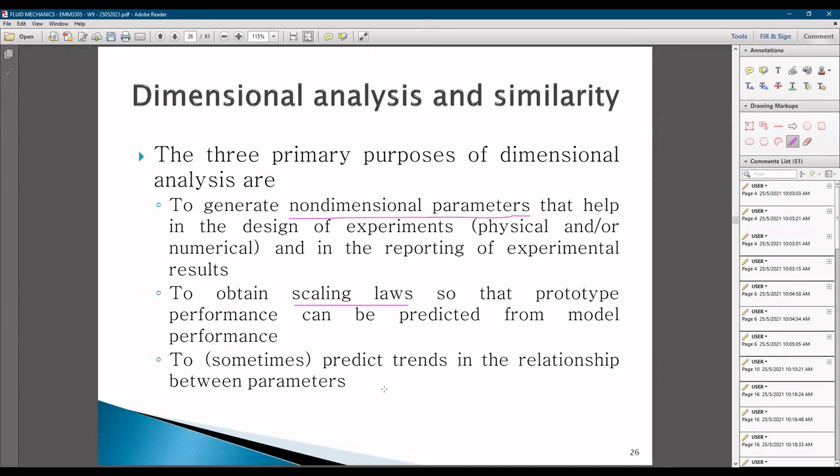Let's say at point A the velocity is very high, and at point B the velocity is low, and you can easily notice that at point A the velocity is high and therefore the pressure will be low, right? And at point B the velocity is low and therefore the pressure will be high. It must work that way for any incompressible flow, right? As long as it satisfies certain rules. And that is what is shown by the Bernoulli equation, actually, right?